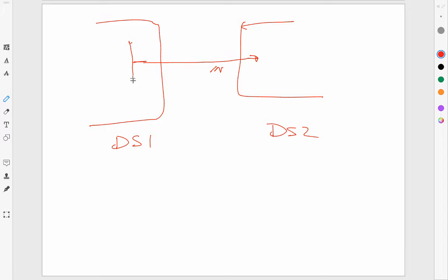Let's imagine that this signal is coming from a state register which is inside here. Let's further imagine that this signal goes to some combinational logic, which in turn affects the next state of this hardware. And this combinational logic probably also makes use of the current state. Okay, so that's the structure we have. So we have a signal coming from one state machine. It is feeding into a second state machine and affecting this next state.